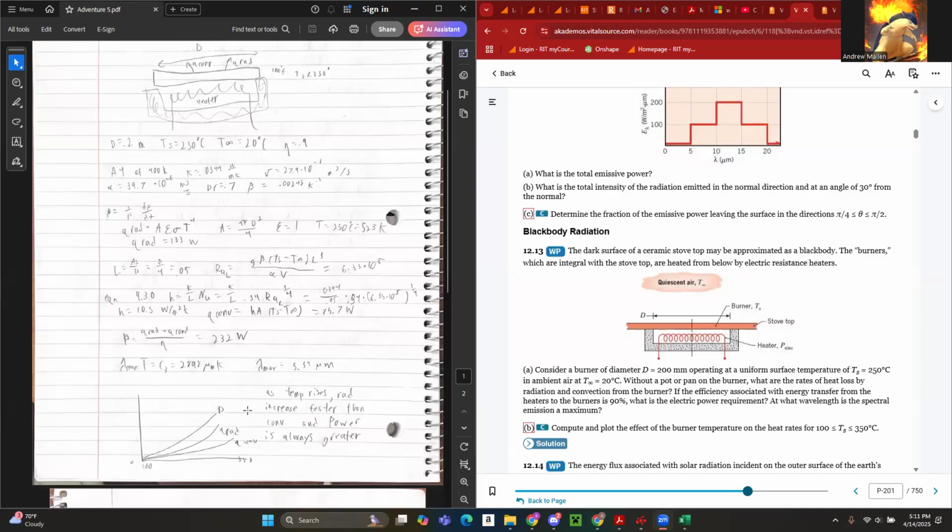So convection is the lowest, radiation is the highest, and of course, the power on the other side of the equation is going to be even greater than all that, because if you add the radiation and convection heat losses together, it is only 0.9 P, or 90% of the energy that the heater is putting into the stovetop, which creates a graph that will look something like this.